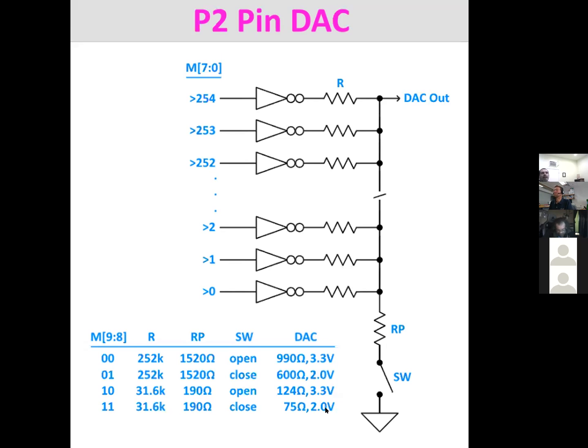And this DAC, the way we built it in the chip, has flip-flops that drive all of these inputs to these inverters. And these flip-flops all register at the same instant. So all of the thermometer decoding is done in logic before the flip-flop, so that when the flip-flop updates, all parallel outputs change at once. And within about 2.5 nanoseconds, this thing settles down to within an LSB. It's super fast.